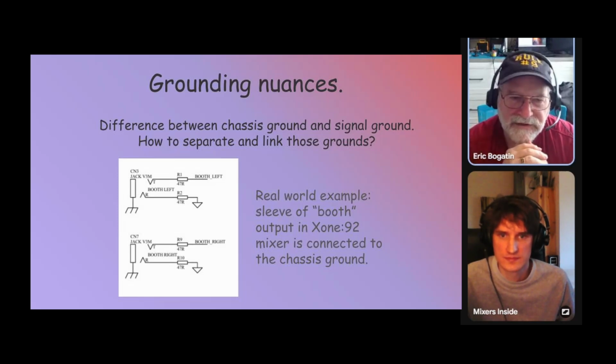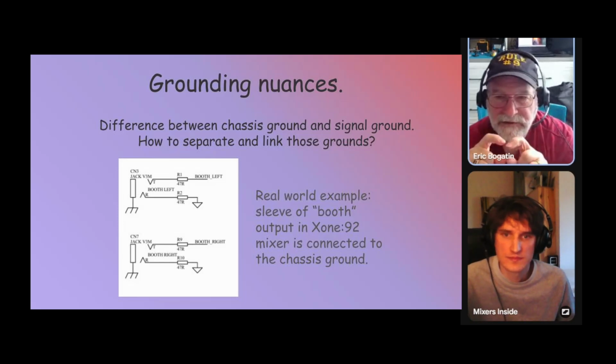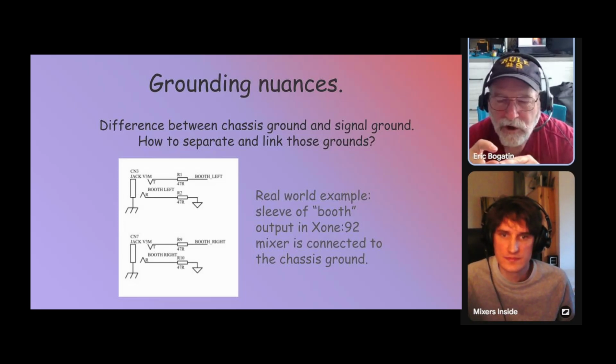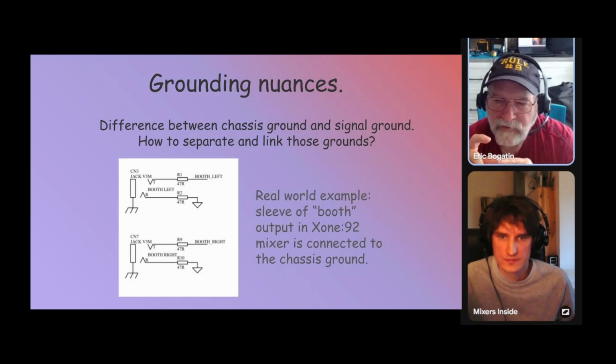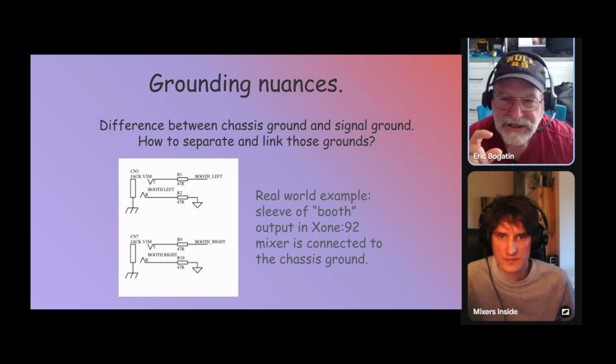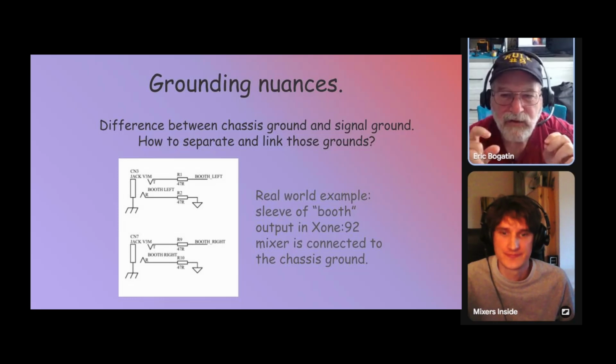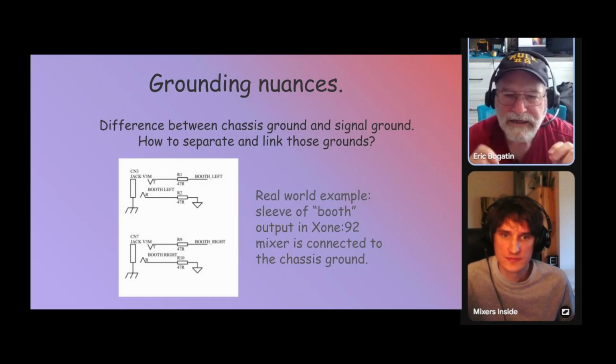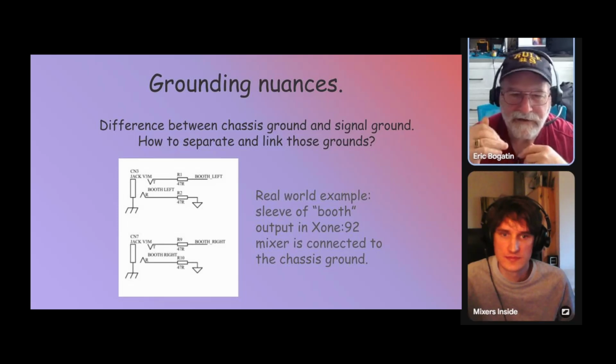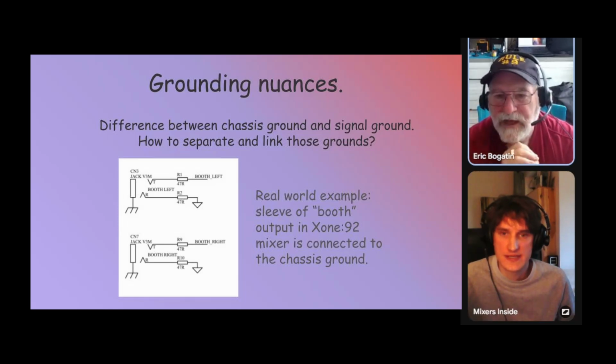Here's where the problem arises. Now your preamp has the two signals, the differential signal coming in, but you're calling the low side circuit ground. And now at your amplifier, if you use a single-ended amplifier, as most of them are, it's got its own local ground reference. And if its local ground reference is a different voltage than the chassis, now that voltage difference between the local ground and the chassis is in series with your signal. And noise between your chassis and local ground is going to cause noise on top of your signal. I see. That's the problem.